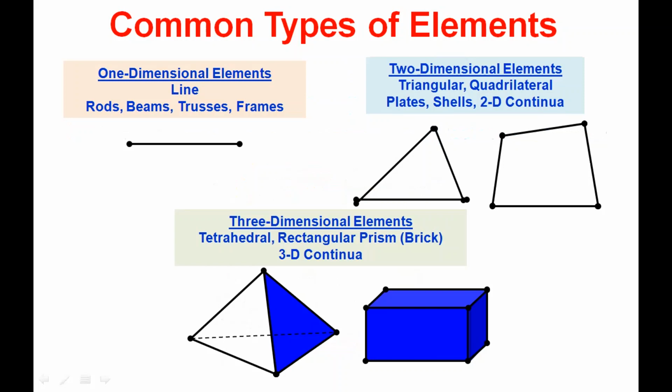In the finite element method, there are different classifications of finite elements, but the major classification is based on the dimensions of the element: one dimensional element, two dimensional element, and three dimensional element. Elements are classified this way because, in an engineering problem, if the field variable is varying along only one direction, let us say the x direction, then we have to use a one dimensional element to solve the problem. Examples are the rod problem and the beam problem we are going to discuss.